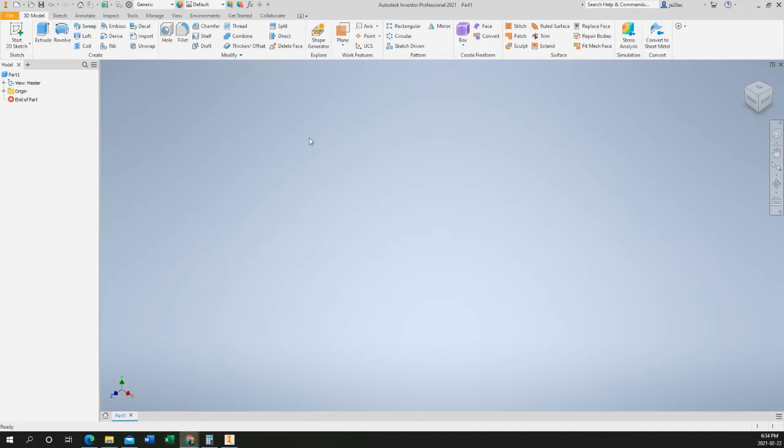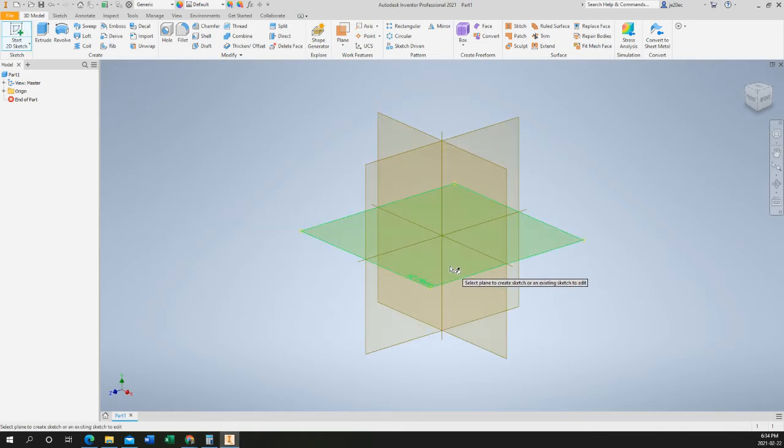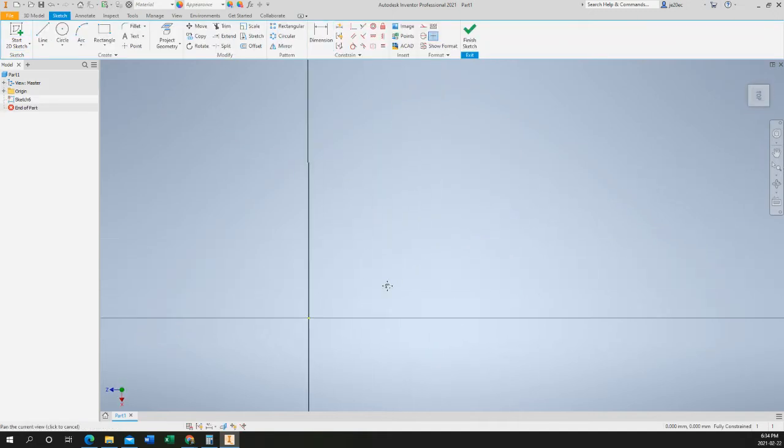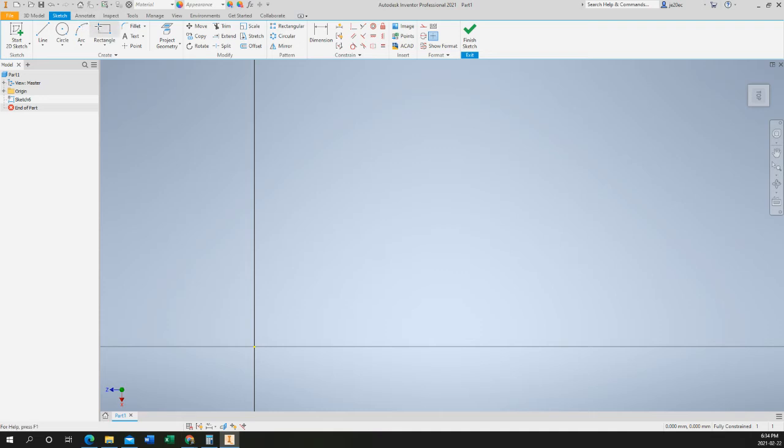So I will start in my 3D environment by creating a new sketch, and I'm going to put it on this XZ plane. Pan over and select my rectangle tool. I will start at the origin and we'll simply draw two rectangles. This creates the T. We'll trim out the line inside that we no longer need, and we'll start applying dimensions.